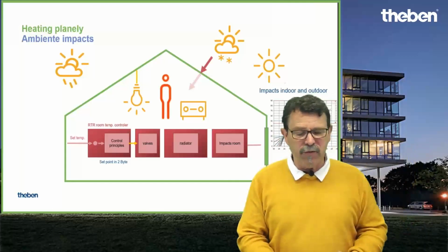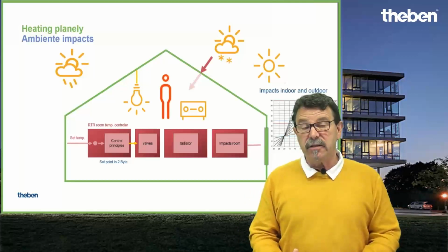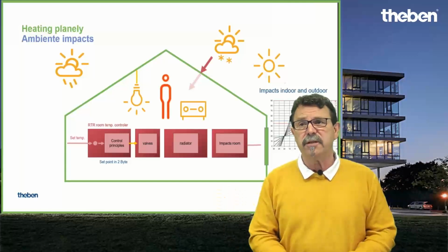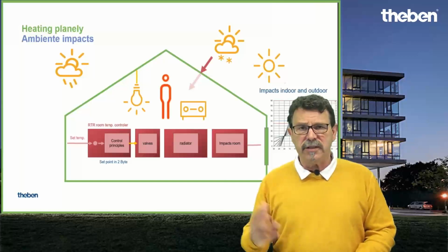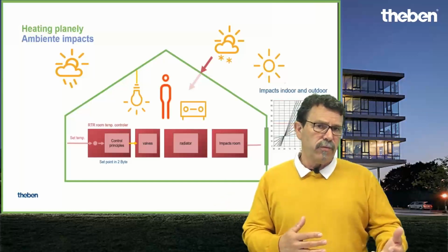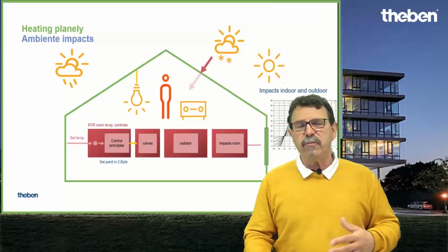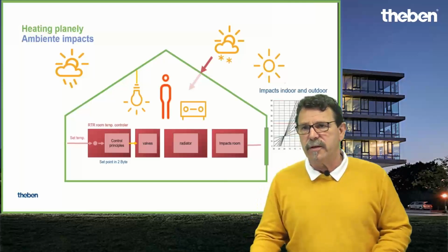For instance, this is an office building, so we measure the current situation, the status, for instance, whether a window is open, yes or no. If you have a smart RTR, you can link a window contact directly to the RTR, and the RTR controls comfort mode or frost protection during the time when you do natural airing by opening a window.